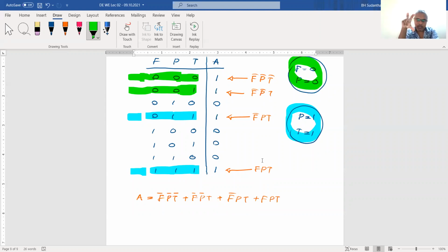After that you can prepare the truth table. For all cases so far we have prepared only 3 variable truth tables, but later you will have a chance to prepare 4 variable truth tables also. It doesn't matter whether it is 2 variables, 3 variables, or 4 variables. According to the number of inputs you need input columns, and according to the number of outputs, you need output columns. Then you have to extract the conditions from the question and mark all these things on the table.